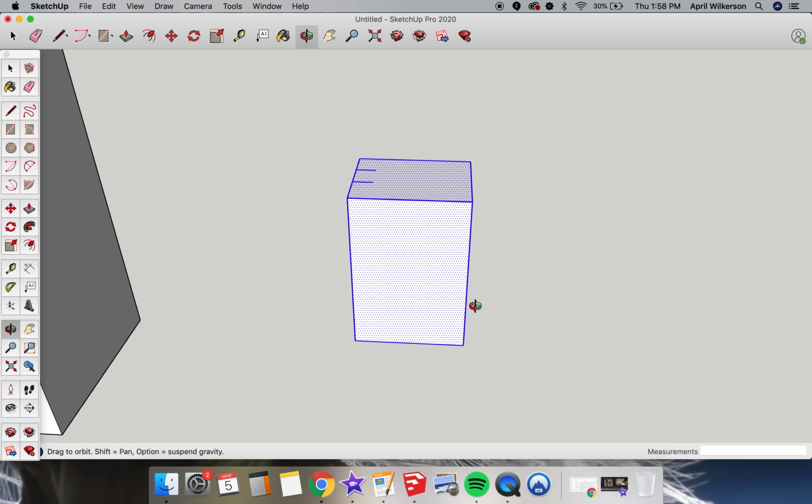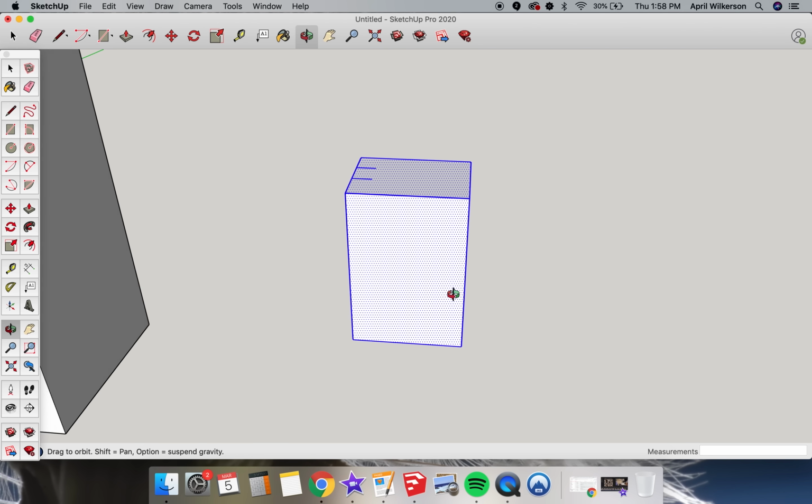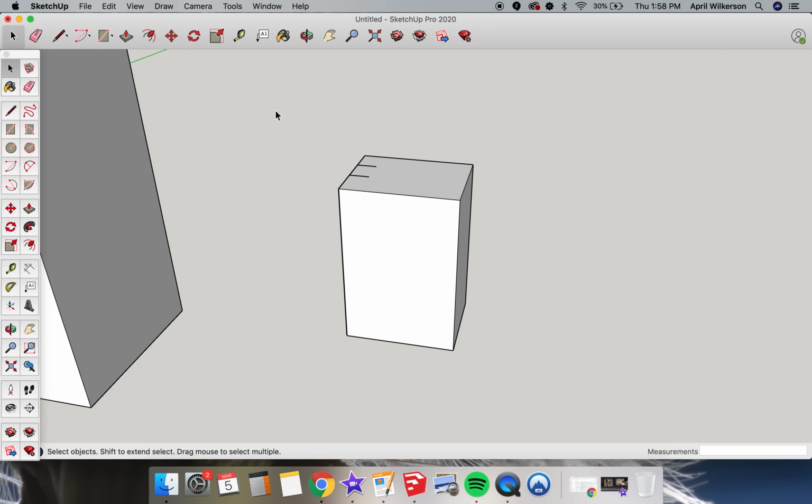Note, there are two different boxes you can create with this tool. If you drag your mouse from left to right, it creates a solid line box, and only parts that are 100% within this box will be selected. However, if you drag the mouse from right to left, a dotted line box will appear, and anything inside the box or anything it touches will be highlighted. This is a sneaky feature that really comes in handy when you have a built-up model.